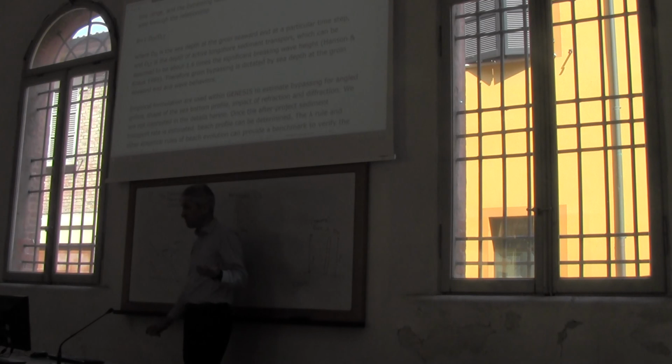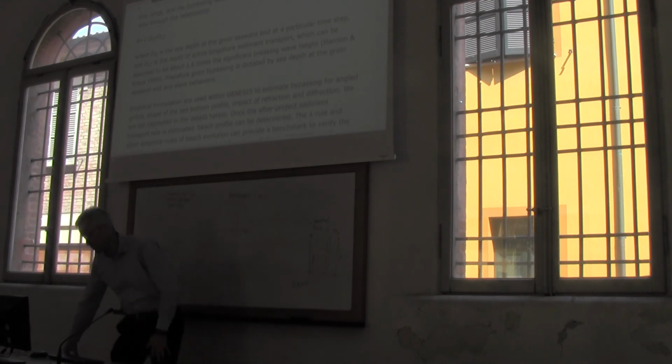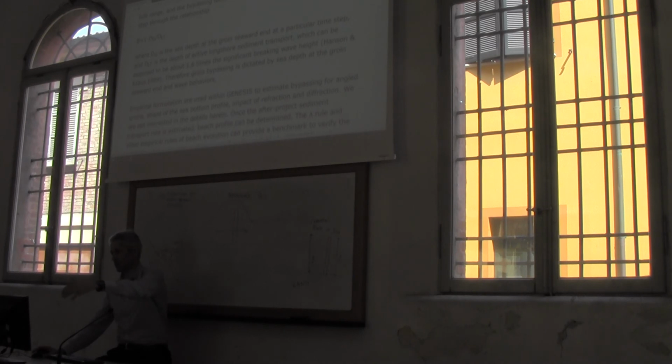So it's just an empirical relationship, and I suggest that you try to see what happens in other patterns of groins, and if you want to take a precautionary estimation, my suggestion is not to make a groin that goes into the sea for hundreds of meters, just take a bypassing factor that is a bit higher.